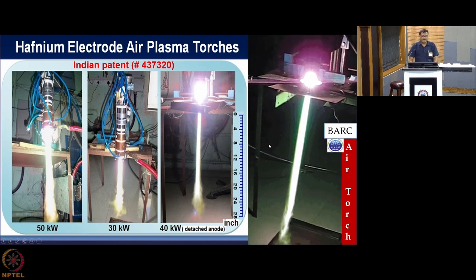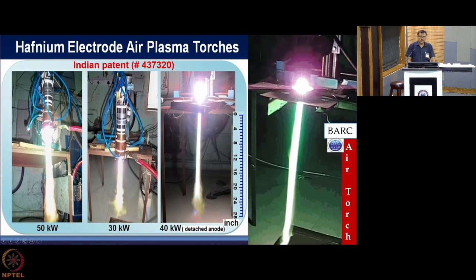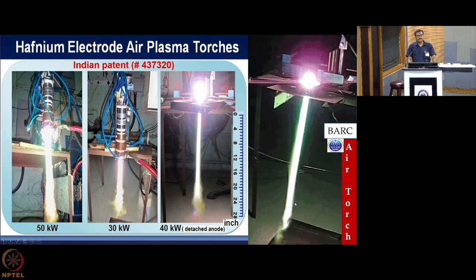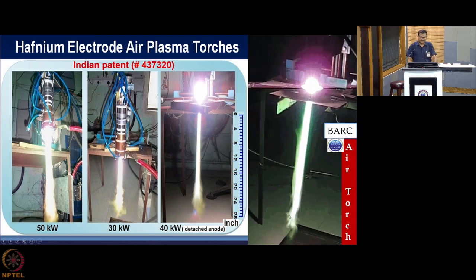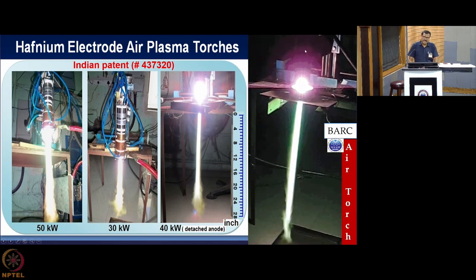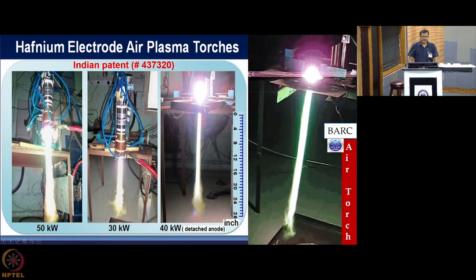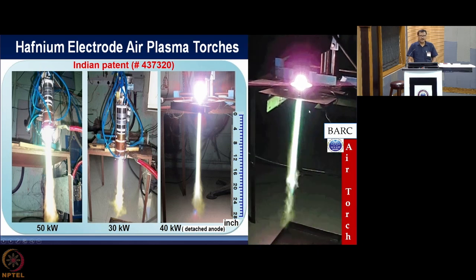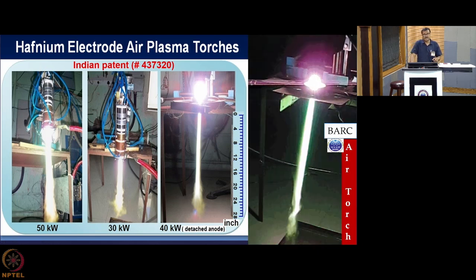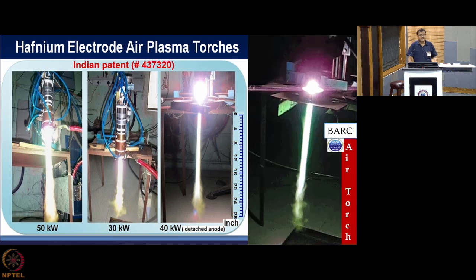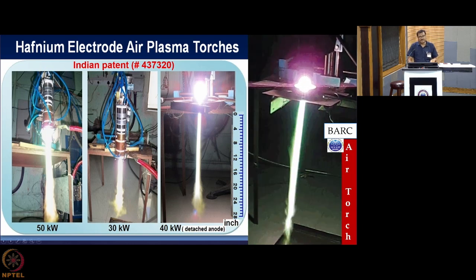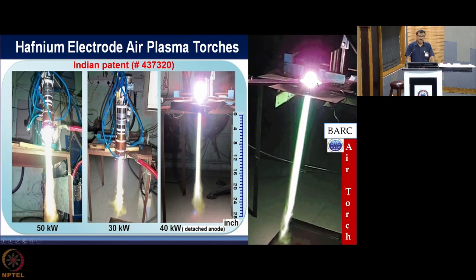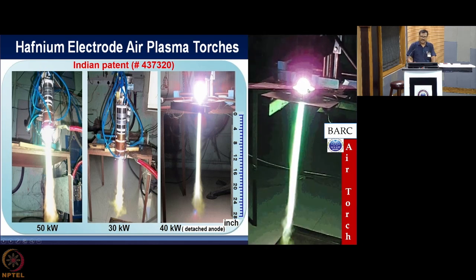Now this kind of plasma device, which can develop such a long plasma plume, is basically a manifestation of the electromagnetic body forces which occur inside the plasma device. Now, when a plasma arc is operating, the arc current is really high. It is easily more than say 200 ampere or maybe 500 ampere. They are very common figures in these arcs. Now, this high current produces a very strong magnetic field.